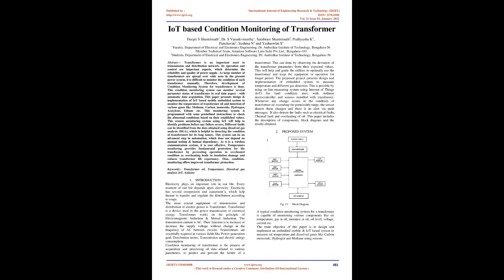Temperature monitoring provides fundamental protection for the transformer by preventing operation in overheated condition, as overheating leads to insulation damage and reduces transformer life expectancy. Thus, condition monitoring offers improved transformer protection. Keywords: transformer oil, temperature, dissolved gas analysis, IoT, Arduino.